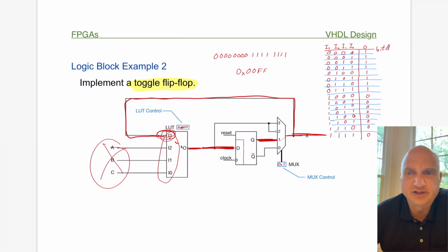Like we said before, you can use this knowledge to your advantage. So if you're trying to create a very optimized design inside an FPGA and you're starting to run out of room, you can do fun little tricks. For instance, let's say that you're creating a state machine with a number of states. In a register intensive machine, you could do what's called one-hot encoding, which would give each state a bit, and since this is a heavily register intensive device, there's tons of flip-flops, you can reduce the number of LUTs you use significantly. So you can have a significant impact on LUT usage.